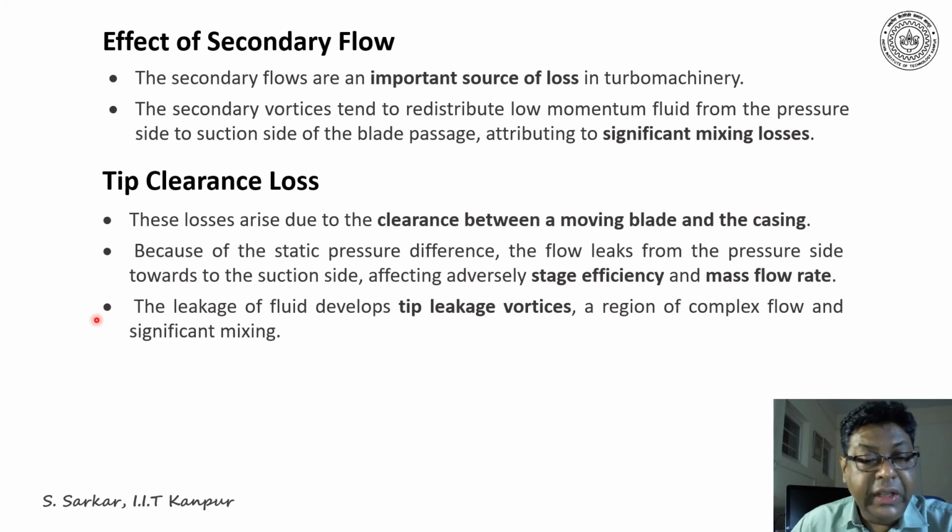Furthermore, the leakage fluid develops tip leakage vortices, a region of complex flow and significant mixing, which creates losses.